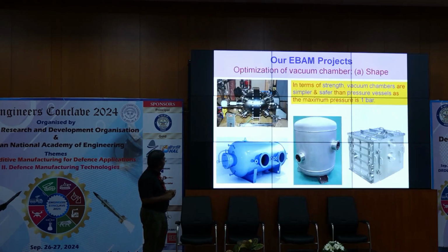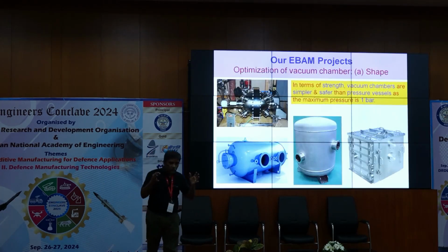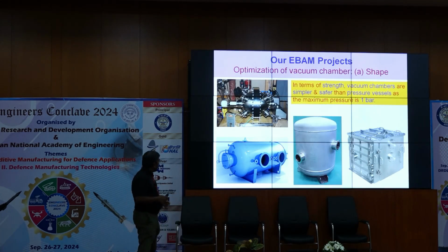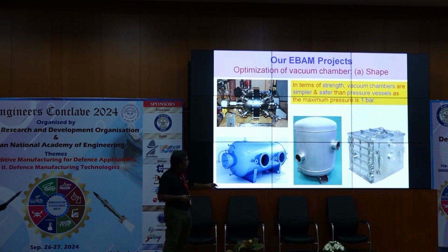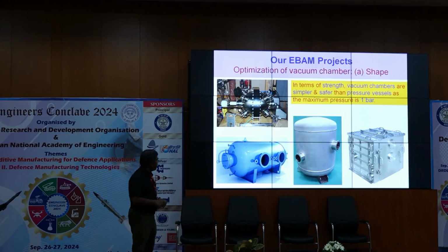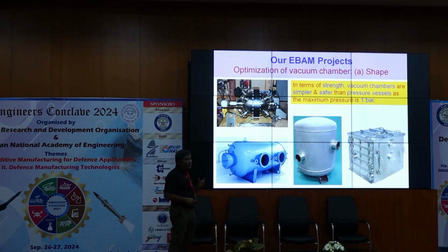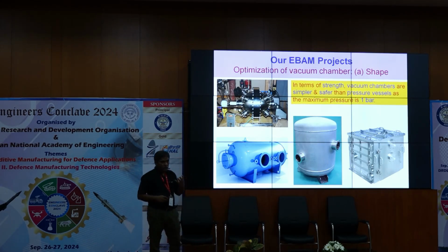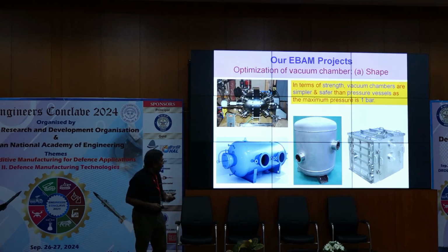Next please. Okay, so we will talk about the shape design. Typically, we are going to put motion systems inside, so we designed a rectangular box as our system. But ideally, if you ask a mechanics expert, he would prefer spherical geometry. Next best is cylindrical geometry. Box is the last. Then you need to put a lot of ribs, and your thickness will be very high.